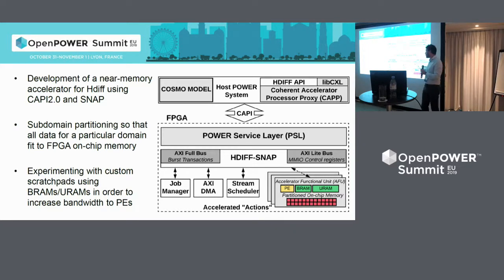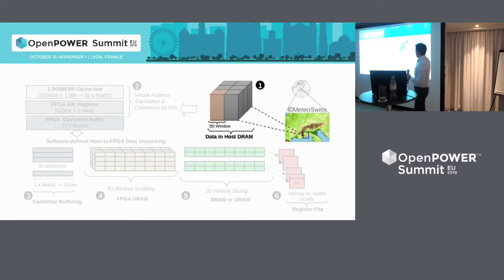So what we've proposed in this work was to partition these memories in a way so we can control the partitioning with Vivado HLS very easily. Then we've partitioned the memories in a way to increase the memory bandwidth between the on-chip memory and these accelerators. And for this work, you can use either block RAMs or ultra RAMs, which offer higher density on the Xilinx FPGA devices.